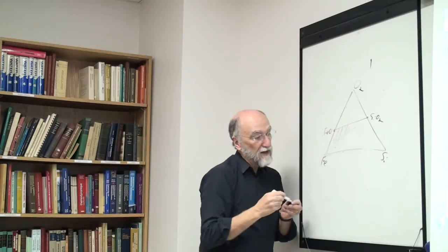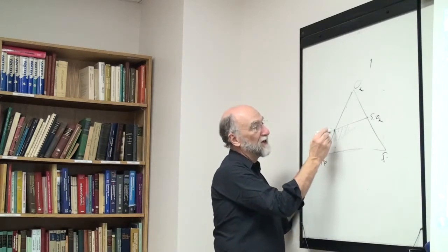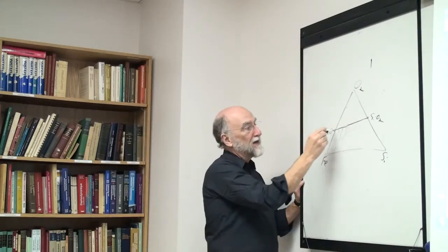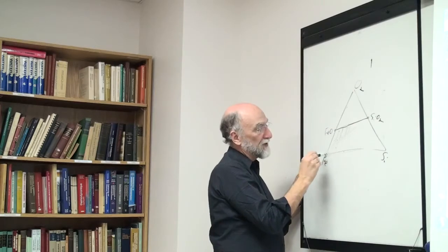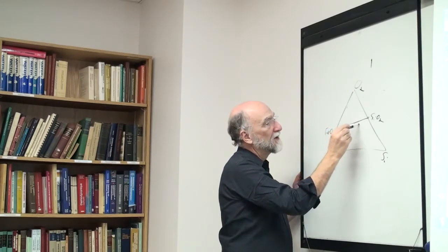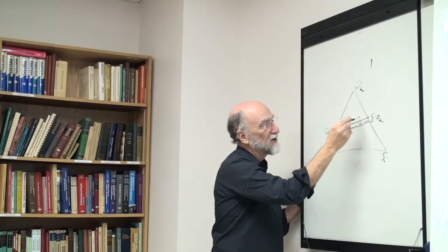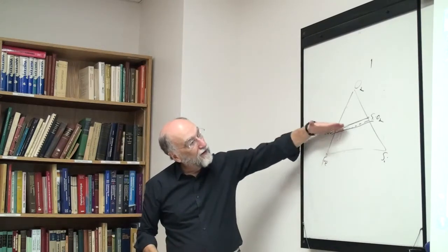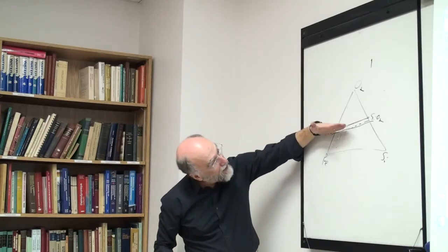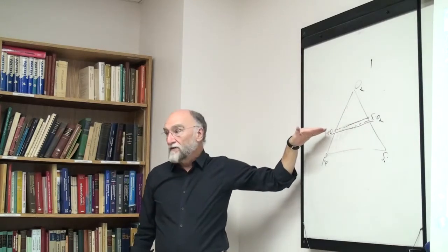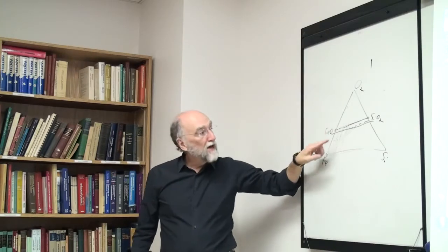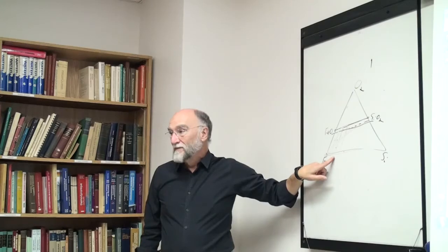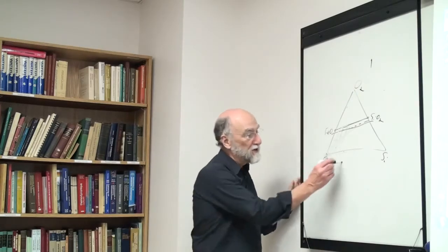What I like to do is calculate it as an isoplethal section. In other words, like the first diagram, the Fe3O4 SiO2, you make an FeO SiO2 plus a little bit of extra iron, so that you're actually calculating a slice very, very close to the FeO silica diagram. So you're getting a vertical section, which is just a little bit on the metal side of the FeO SiO2 diagram, in order to assure that you've always got a metal phase present.